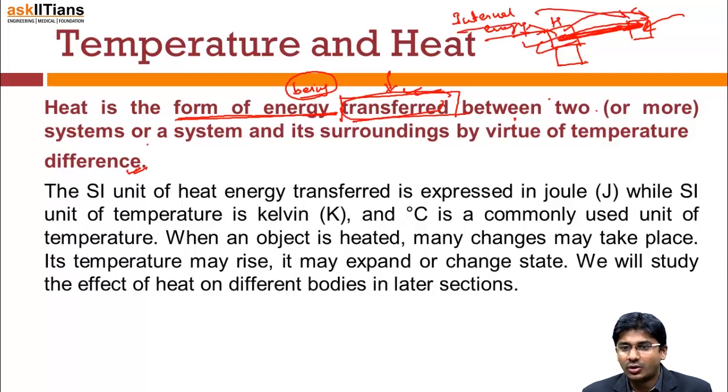And so it is called heat when it is in the cold body. So there is no such thing as this much heat being contained by a body, or this much heat contained by another body, or this body contains more heat than another body. These are all wrong statements. What they contain is the internal energy. Heat exists only when, for the time being, it is being transferred. So heat is the energy in transit. It's only the energy in transit, nothing else. Be very clear with this definition.